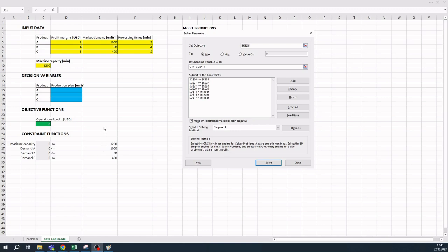Another thing that we need to provide to the solver is the objective function itself. We will tell the solver inside the solver settings whether the problem should be maximized or minimized, but we need to provide a cell that contains a function for calculating the objective function. So we need to model the objective function in a cell. Again, you can put this cell wherever you want.